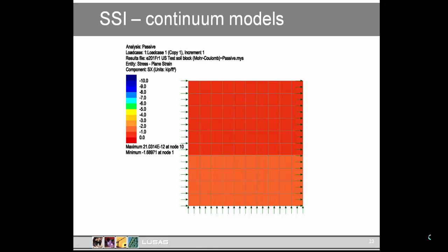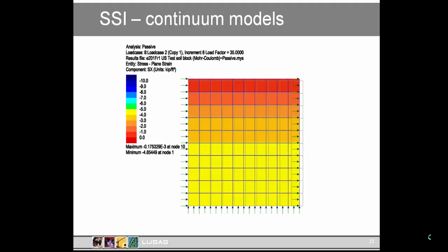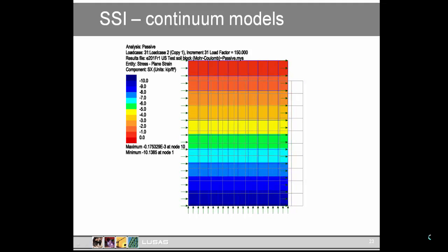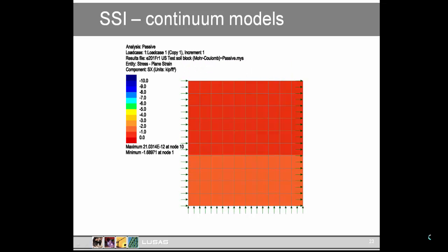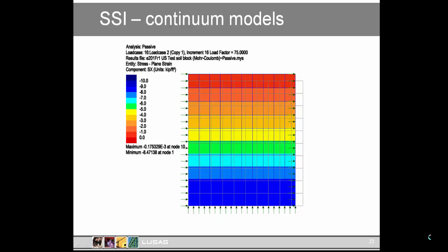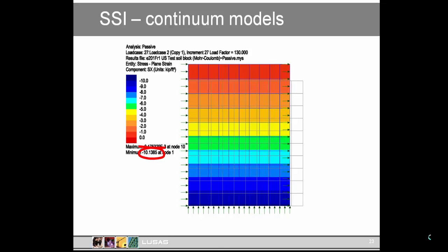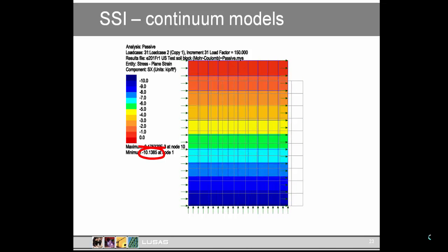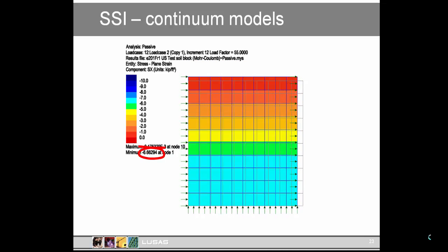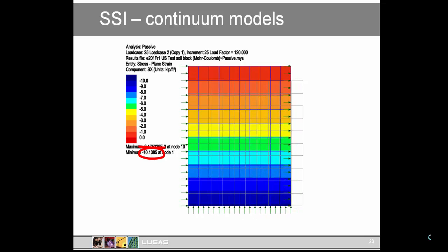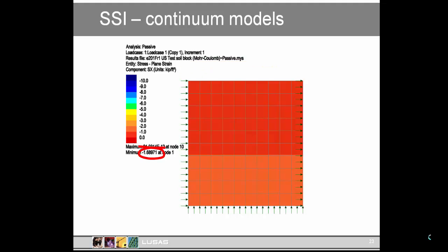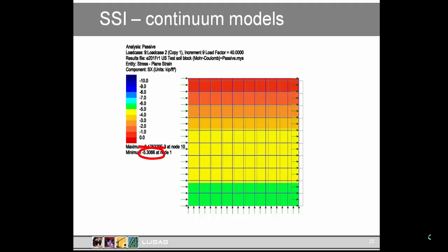So here's the block. We move the right boundary as if it's an abutment wall being pushed into the block by some thermal expansion. Stresses in the soil increase. Finally, they reach the expected passive pressure and they don't exceed it. We could do the same in reverse and find the decrease in stress to the limiting active state. These states are reached at a strain, a measurable deflection in this model.